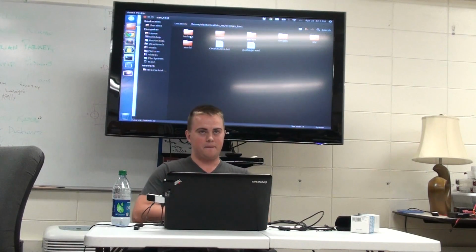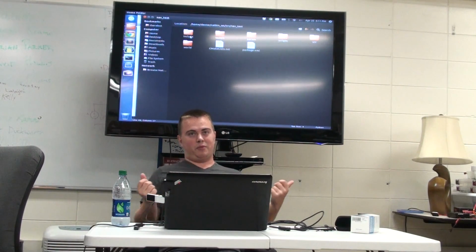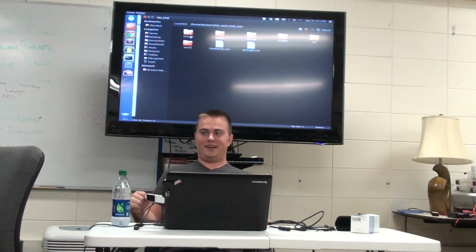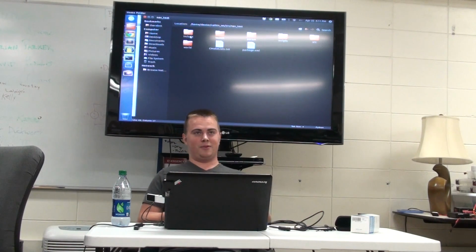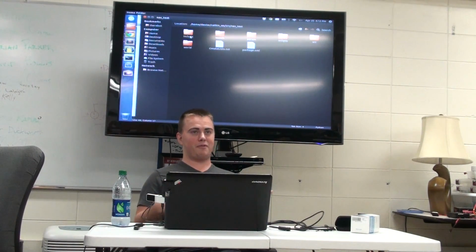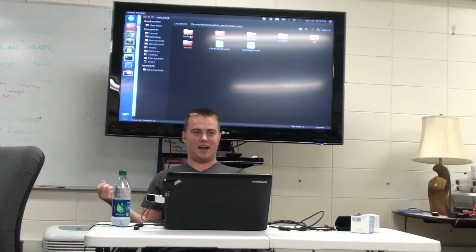So why are we using ROS Launch when we only have one file? The answer is because you pretty much never have just one file. When you're working with robots, you will need to launch one of two things. You'll either need to launch a simulation to pretend it's a robot, so you'll need your program plus a simulation package, or you'll need to launch the appropriate bring up files, the bring up programs that your robot needs,